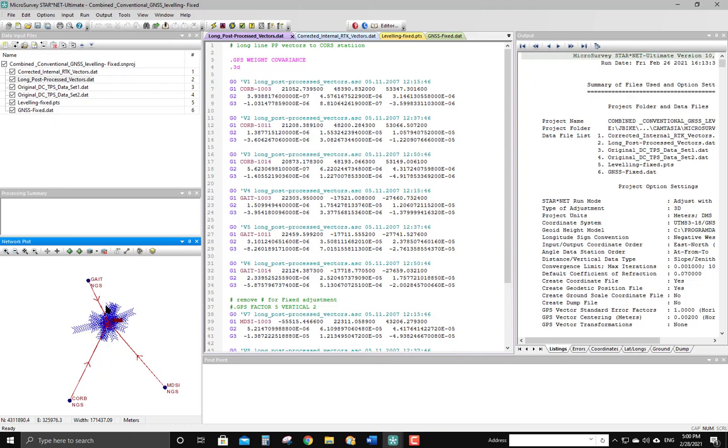What they do is they allow you to assign an orientation and a location for your project that gives it a strong degree of accuracy. And GPS vectors are always weighted against the covariance matrix information that is reported by the software that was used to either post-process it or to process the RTK information for RTK data.